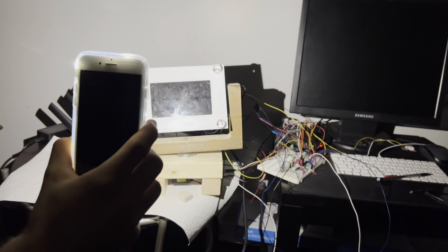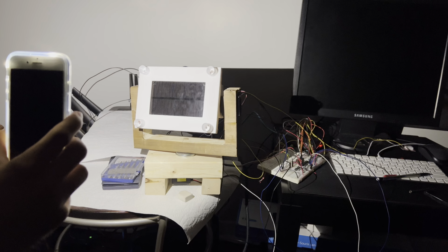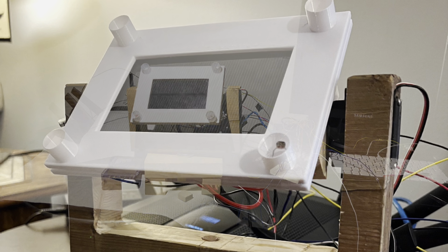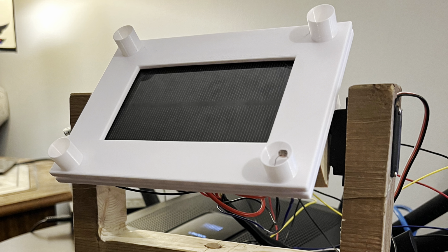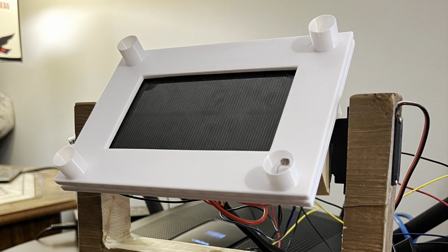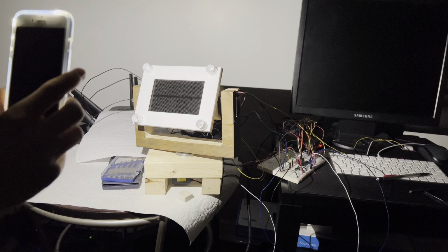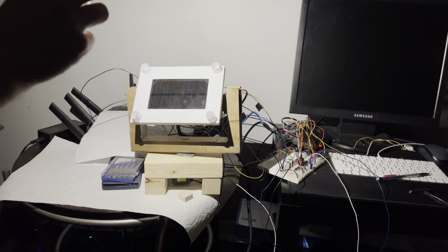The smart solar panel will rotate in the direction of the LDR that is receiving the most amount of light. Due to there being 4 LDRs, one at each corner of the solar panel frame, the Raspberry Pi code will compare the voltage at each LDR since light hitting an LDR causes its voltage to decrease. The servo motors will only stop rotating if the LDRs are at a position in which the solar panel is receiving the maximum amount of light available.